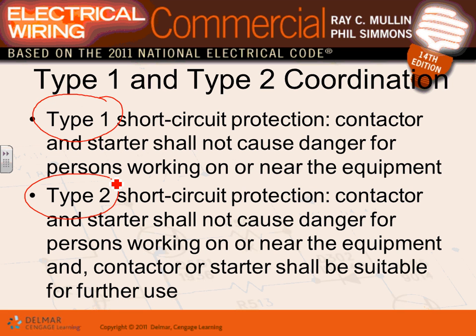Now, which one do you think is the best? Type 2. What's wrong with type 2? You spend more money to get a type 2. So there's type 1, type 2 protection. For example, guys, if you have a VFD and your VFD is $10,000, a VFD on a 100 horsepower motor, do you really want type 1 or type 2 protection? You need type 2. If you have a magnetic starter, big fat boy like this, old contactor, nothing electronic, do you want type 1 or type 2? Type 1. You can see the difference between type 1 and type 2? How important is the controller? Soft start, VFDs, recommendation type 2. Magnetic starters, recommendation type 1.